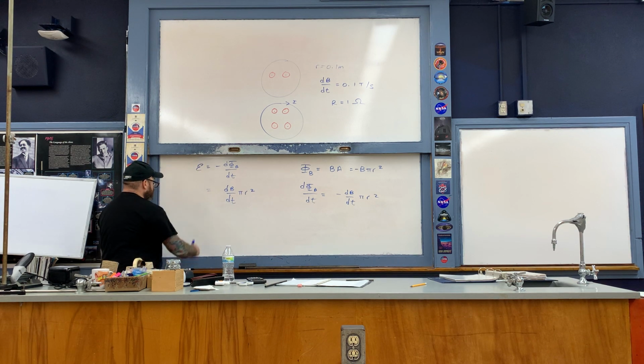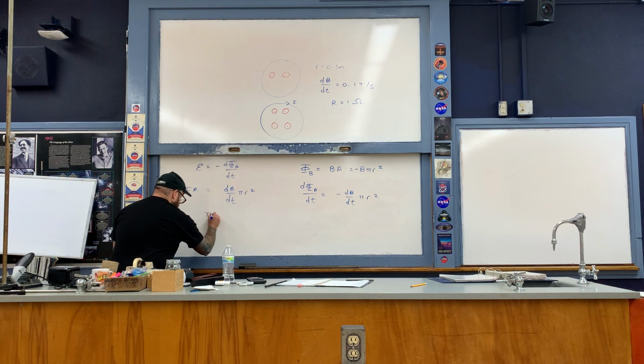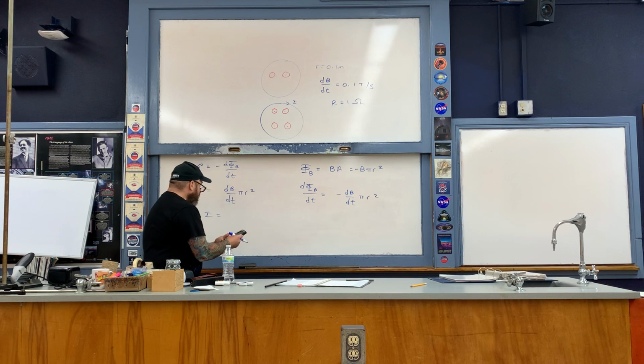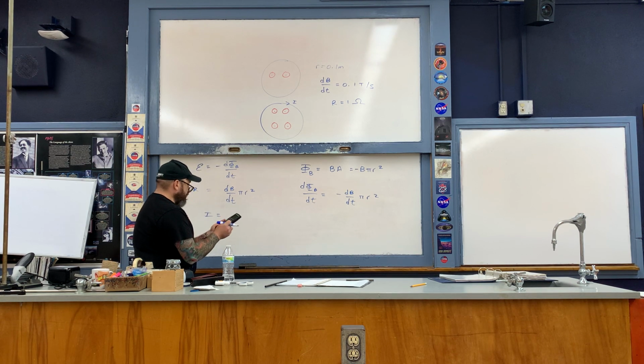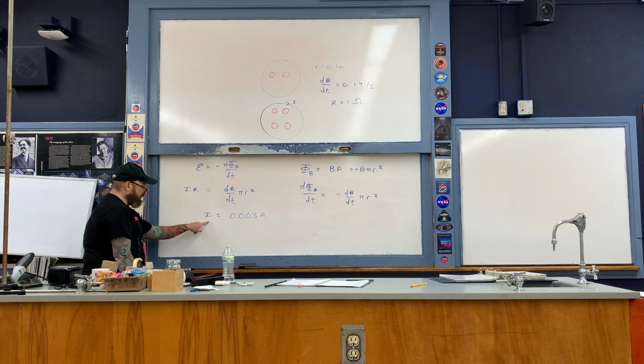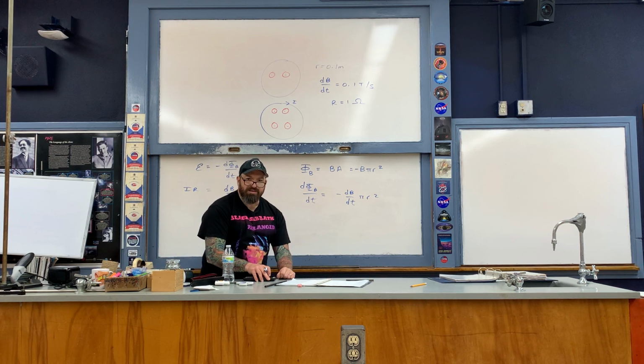Okay, the left-hand side of the expression, the induced EMF from Ohm's law, is just I times capital R, where capital R, the resistance, is just 1 ohm. So let's now calculate the current I. That will mathematically just finish the problem for us. We've got 0.1 Tesla per second times pi times the radius squared, so times 0.1 meters squared, like so. And this gives us 0.003, and then we're calculating current here by dividing by the resistance of 1 ohm. This, of course, is in terms of amperes. So a basic problem similar to the other examples that we looked at.